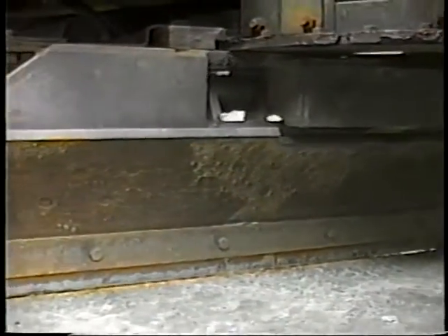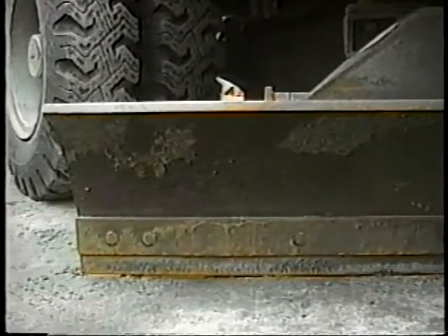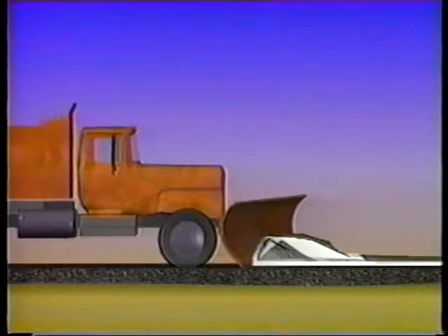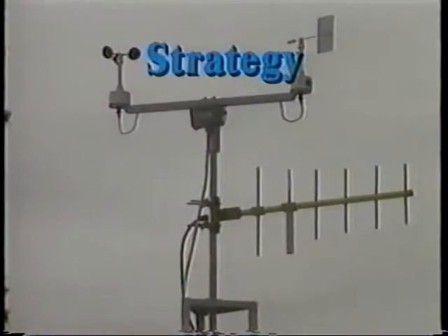Plow cutting edges should ride on the pavement to remove as much snow and ice as possible. Casters or shoes should not be used unless required for safety on certain highway segments. A slush blade behind the cutting blade may be desirable.